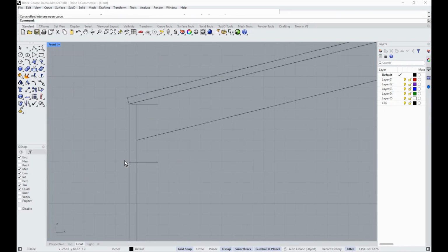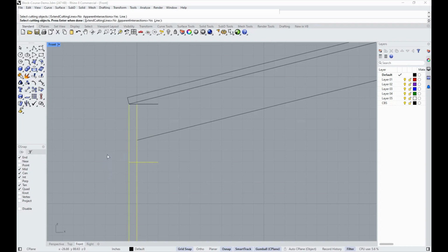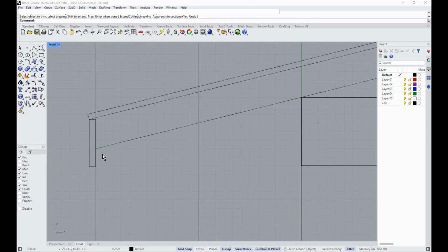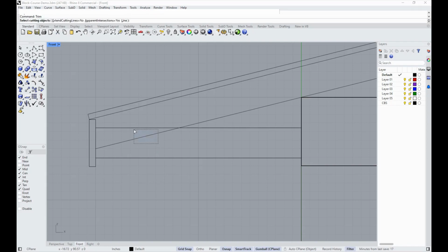Down. All right, so we're going to trim this stuff, and that. Trim. That hangs down a little bit. Depending on who your truss manufacturer is, you can get this kicked up where you don't have so much hanging down. We'll just bring this over. Maybe kick this up by 1 inch and go 3.5 since we're sitting orthogonally to the X, Y, and Z. We'll trim it.